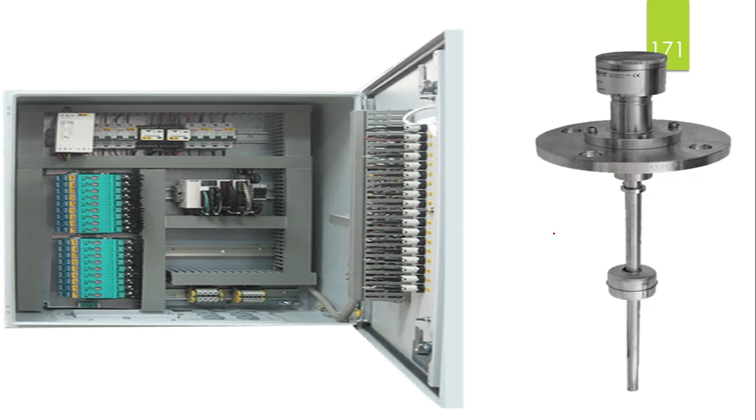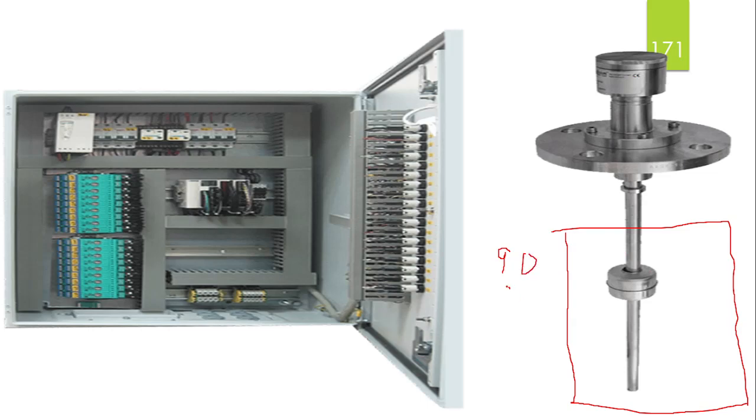Normally each bunker tank is provided with this type of alarm. This alarm is generally provided so it sounds whenever your tank level reaches 90%, or sometimes in some settings it will be 85%. It depends upon the company requirement.